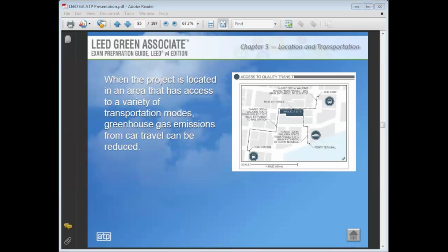But we need to understand that since, why is basement parking a better option than surface parking in terms of LEED? Yes, that's a good question, Ahmed. The reason being this, that with the help of basement parking, you are utilizing that footprint which was already being covered. Since there will be a building on this site, and the basement is going to use the same footprint area, it will help you use the same footprint for an alternate purpose rather than expanding the built area or the paved area around the facility, which is going to reduce the green areas.